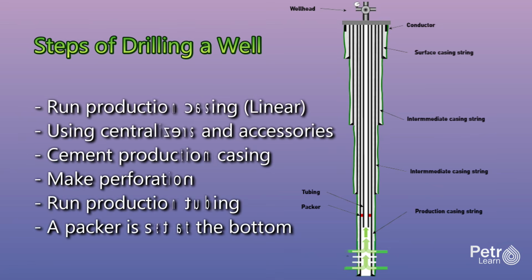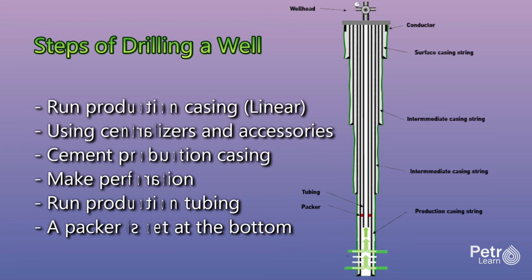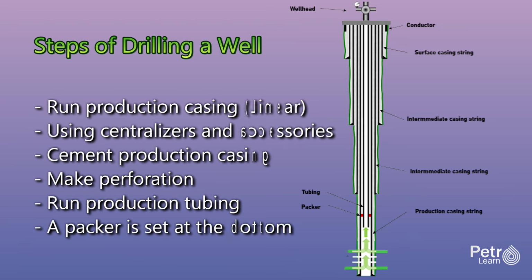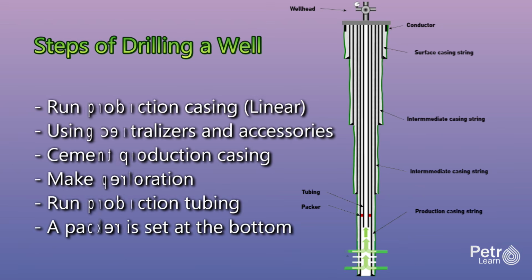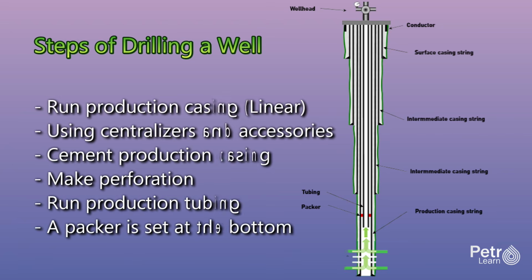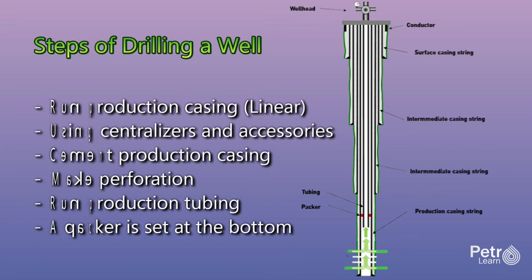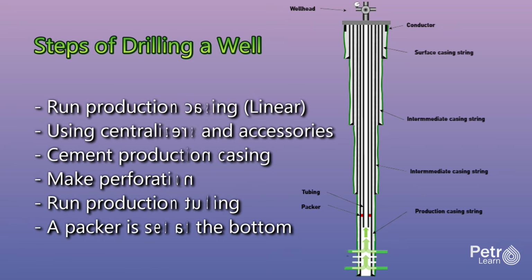The perforation plan specifies shot density, typically 4 to 12 shots per foot, and phasing, which is the angular spacing of shots. 0-degree phasing puts all shots in a single line. 180-degree phasing alternates shots on opposite sides, and 60-degree or 120-degree phasing distributes shots spirally around the casing. Phasing affects the stress distribution around the wellbore and can impact sand production.